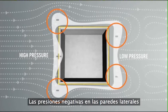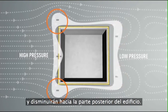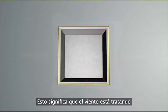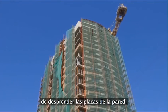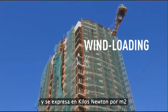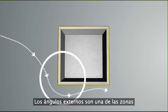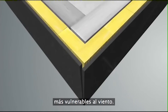The negative pressures on the side walls will generally be greater at the front end and reduce further back along the building towards the rear. This means that the wind is trying to pull the panels off the wall. This is known as wind loading and is expressed as kilonewton per metre squared. External corners are one of the most vulnerable areas to wind.